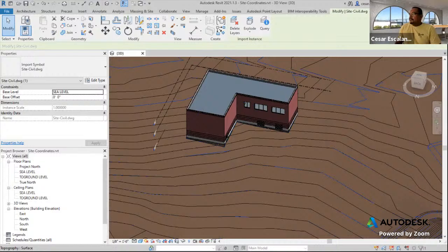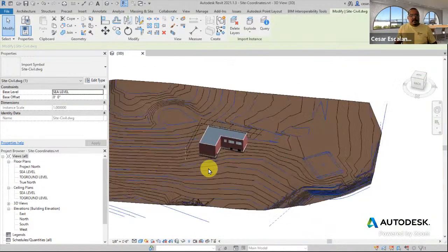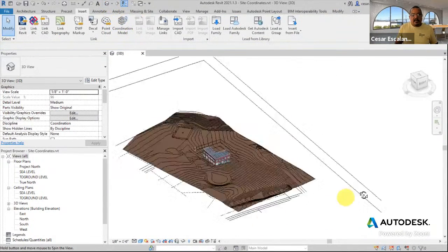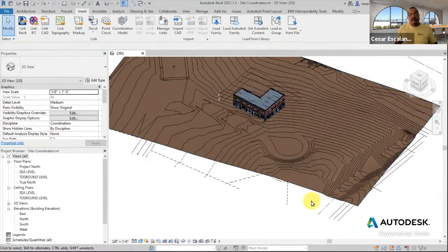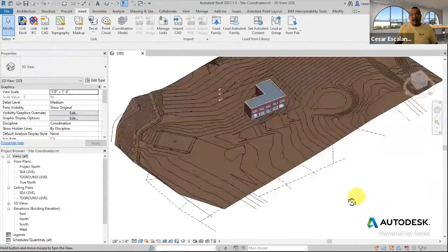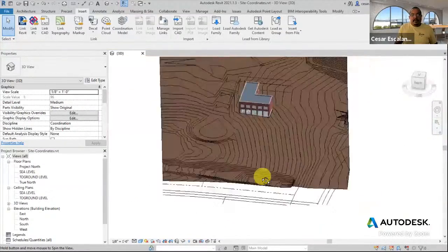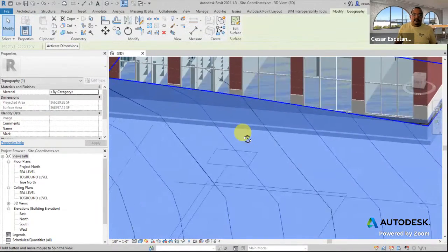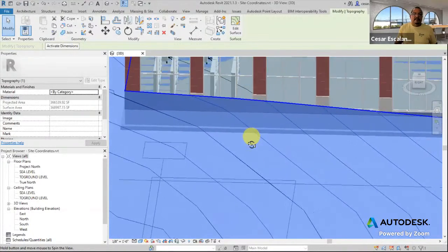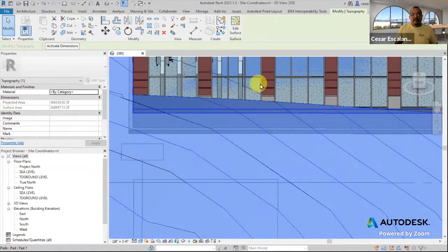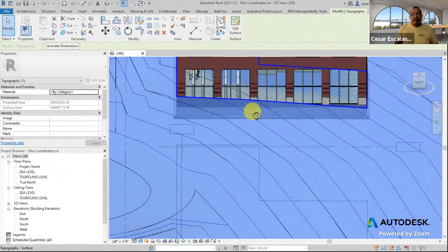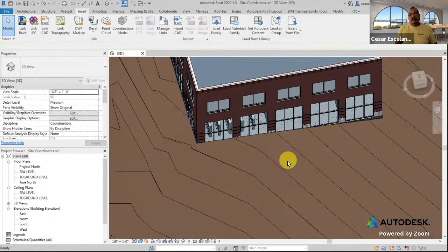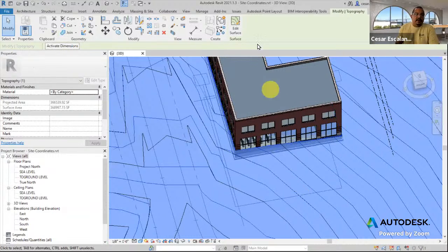All right. That is the typical process of establishing shared coordinates. I added the extra topic of topography using existing elevations from contours. One thing you may notice here is, for example, that the site is encroaching, overlapping the facade of these elements. And if we want to modify that, then we need to start getting into the business of grading.